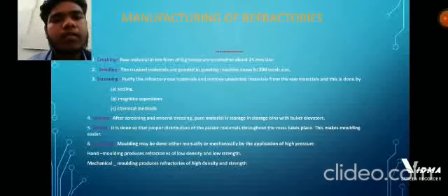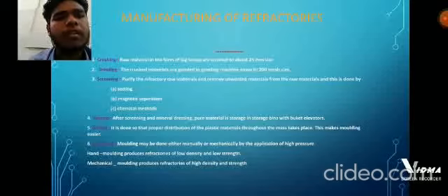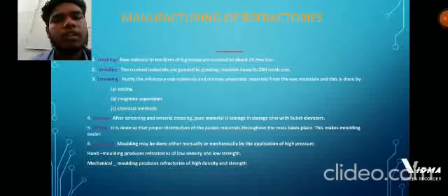6. Molding. Molding may be done either manually or mechanically by the application of high pressure. Hand molding produces refractories of low density and low strength.